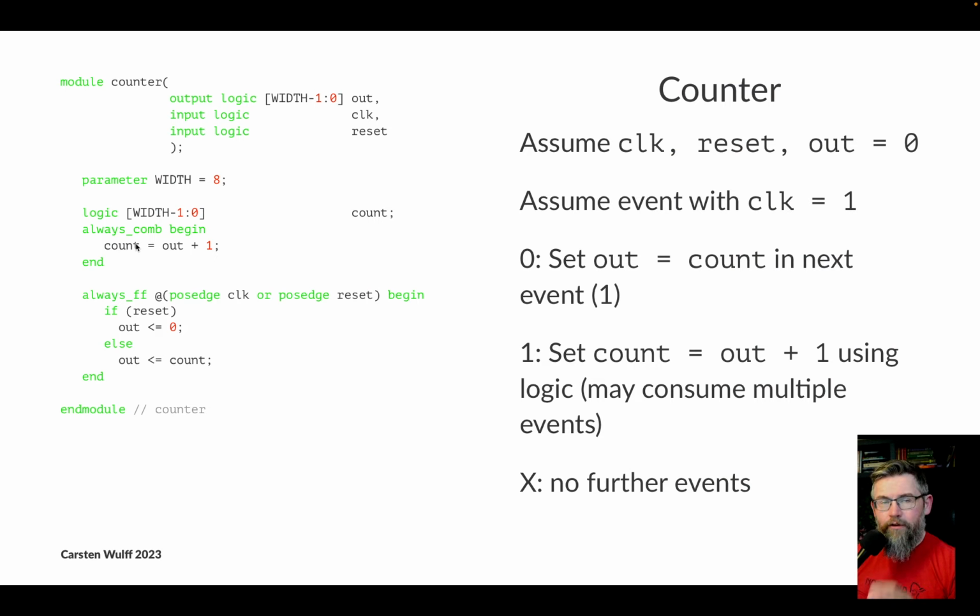And if you use any of the old constructs in Verilog, like always, you don't really know what the code will... Well, you have to write the code in the right manner to get the right type of logic. But when you use always_ff and always_comb, then SystemVerilog and the compiler will help you ensure that you end up with combinatorial for the always_comb and synchronous for always_ff.